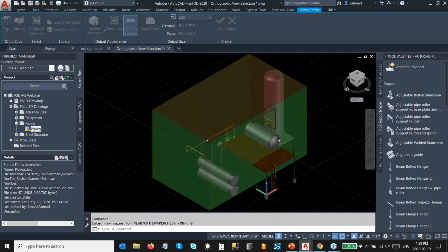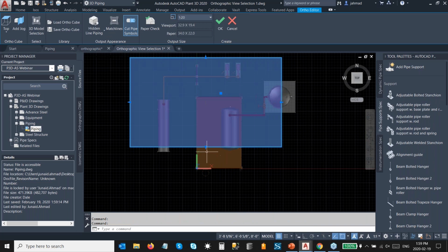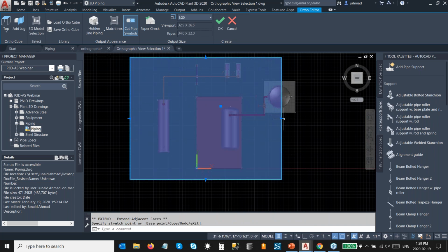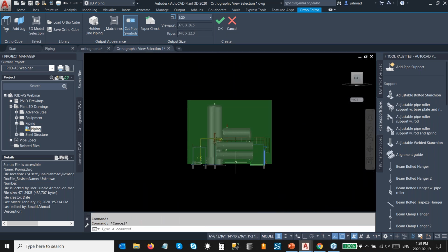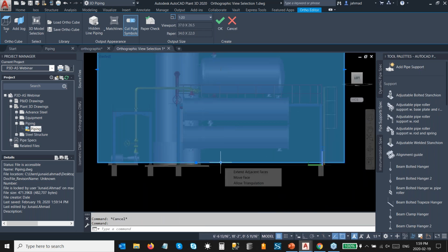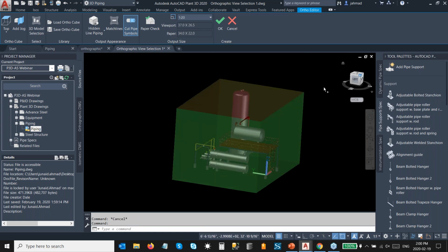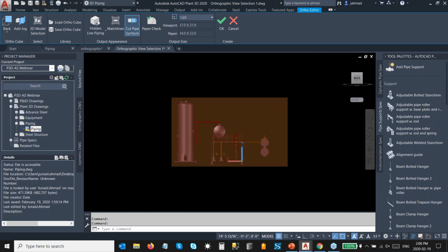Click OK. The program does a refresh, and I'll use the navigation cube to make some adjustment to the length, width, and height of the cube, just so we make sure that everything shows up on the viewport. And I'm going to make some adjustment to the ortho cube here on this side as well. Okay. And I'm thinking to create the orthographic drawing from the back, which is on that side. Let me actually use the navigation cube to go to back.